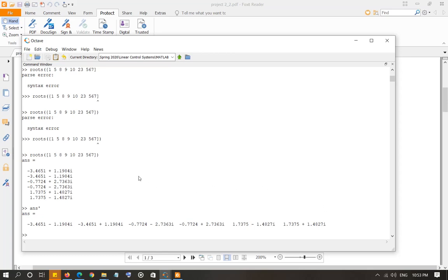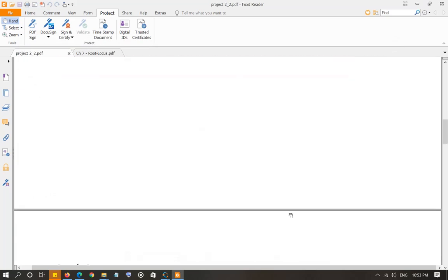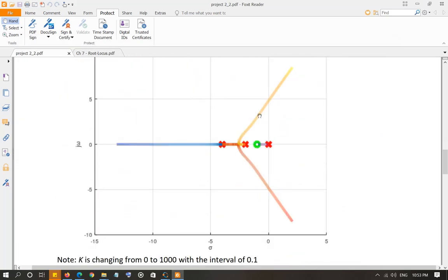So then when you are plotting on the S domain, or S plane, sorry, what do you need? If I go back, let's say this is the point that you're plotting, that means you are plotting x versus y. That is, you are plotting the real part of the root versus the imaginary part of the root.